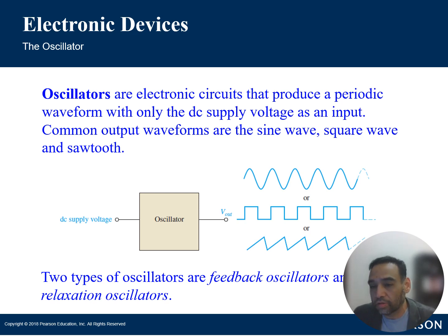The next phase is some type of amplification, right? So the oscillator circuit includes an active component such as a transistor, or as you all are familiar with now, operational amplifiers. And we use these to provide amplification to the signal. The amplification compensates for any loss in the circuit, and it also ensures that the output signal maintains its amplitude.